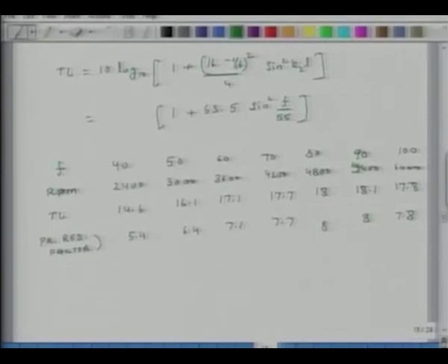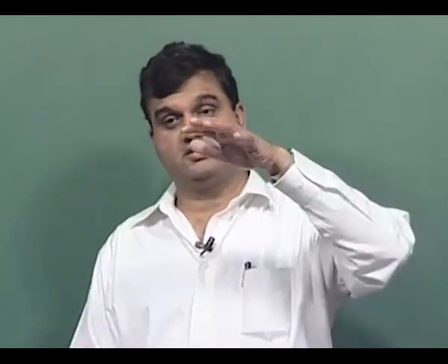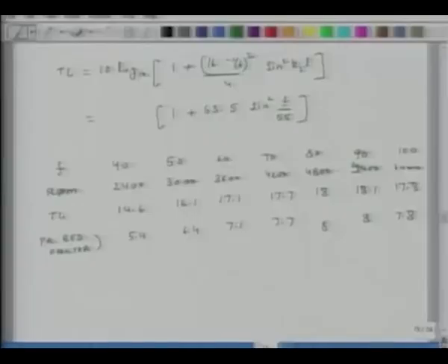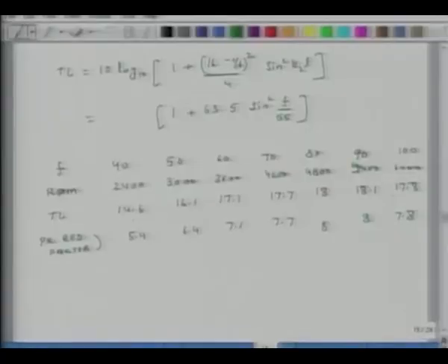So now if you look below the car, if you have more space, then you can make the value of M larger. Or you don't necessarily have to make it round. It could be a rectangular shape wherever you have more space, so that your cross-sectional area is larger. M is basically the ratio of cross-sectional areas. So if I want further reduction in sound, I can increase my M. And I can also check where my maximum noise is coming from, what frequency, and based on that I can change the value of L. Right. So I am getting 14 to 18 dBs of transmission loss.